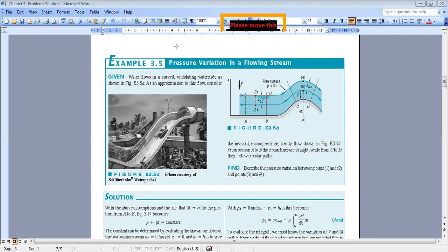You remember when we considered a flow having a certain acceleration in x, for example? Here, why don't you have ax? We don't have an acceleration here because, between these two parts, you have a constant cross-sectional area, and it's a steady flow. So V will be constant between A and B. Why is V constant between A and B?